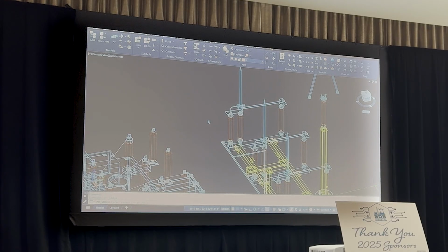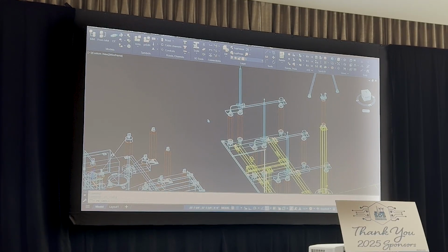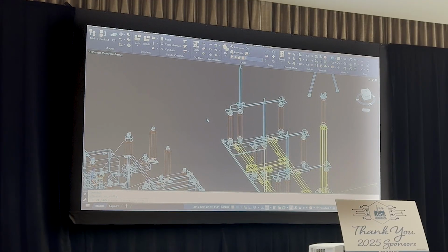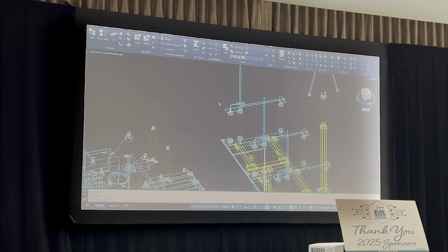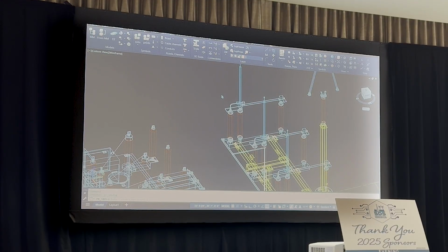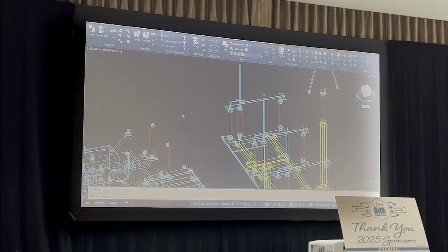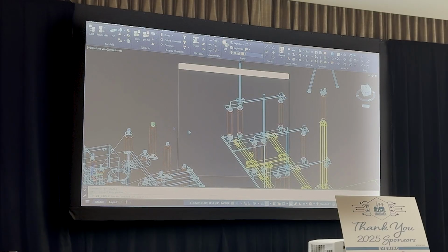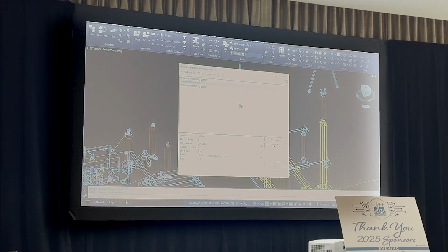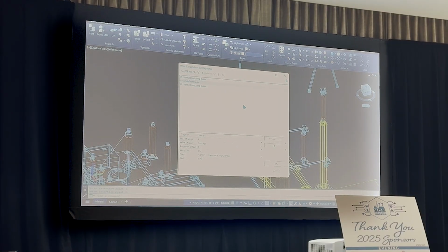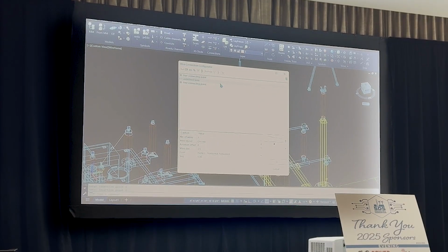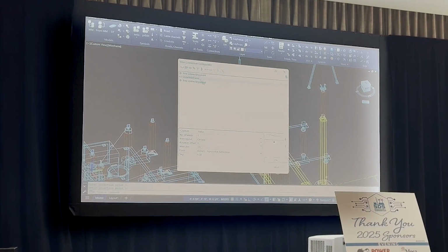We do it for bus because we like to see where the supports are, and we like to have the connections because they offset that bus height. You want to keep that consistent bus height. For cable, you don't necessarily have to put them, but you can. But I'm going to show you the other workflow if you don't put them too. So for the cables, I click that point, I click this one, and you'll see this dialog. This is going to be the same thing that pops up for bus too. So it's going to be kind of consistent here.